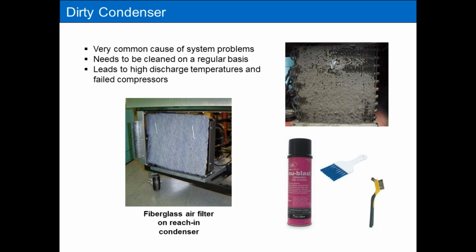And sometimes you're not going to be able to do a good job cleaning them because the grease is rock hard. And there have been some occasions where it might be best practice to just change out the whole condenser or condensing unit if the compressor failed, because you just can't clean the coil. So you've got to see what type of dirt you're dealing with. Is it hardened grease? That's problematic. Or is it just something that could be brushed off?